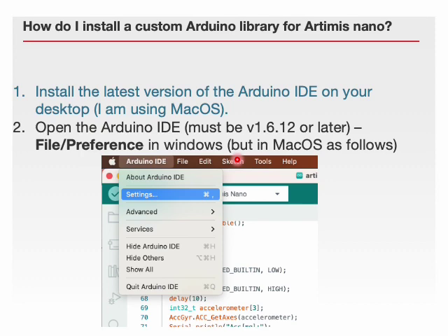We need to introduce our hardware and its libraries to the Arduino software IDE first. I listed here a few steps in detail which are applicable for any type of hardware. First, we need to install and then open the IDE and then install a Sparkfun product by opening the settings menu from the toolbar as shown here.